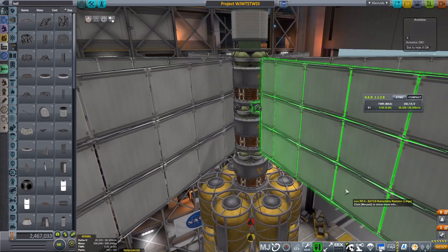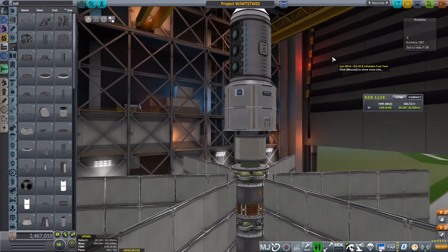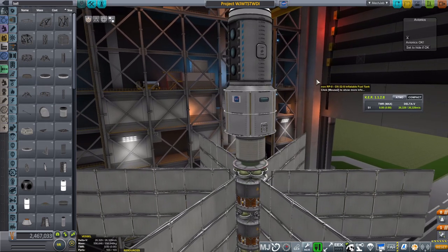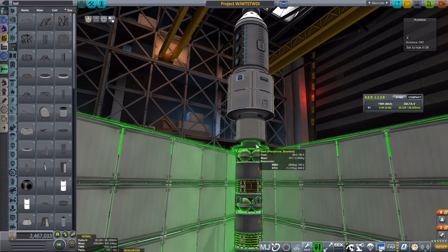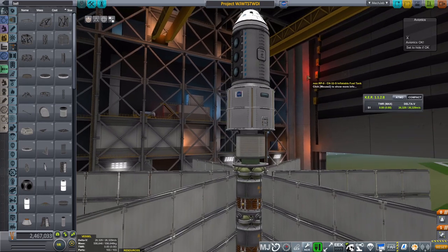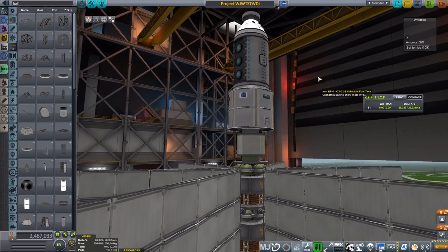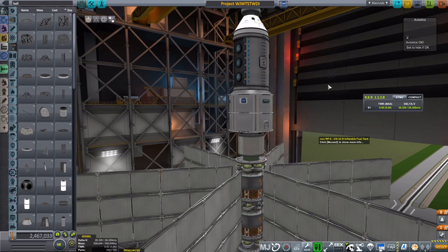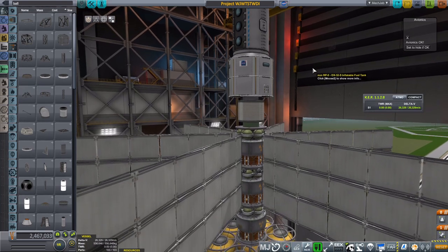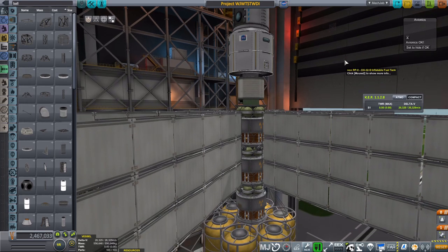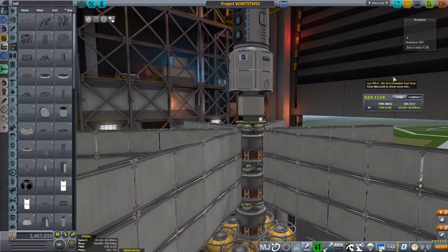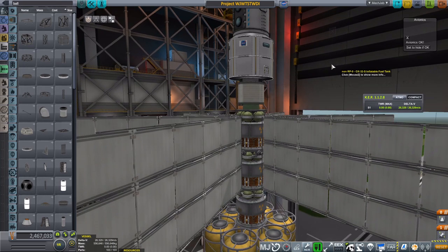It's a little complicated, but in order to undo it, you can have little thrusters oriented radially around the craft. You burn a little bit of fuel, and then you spin down the wheels so they can get back to working again. So that was mass meant to compensate for that. The engines themselves, I didn't have time to throw in the positions and such. But you can imagine like the Apollo Command and Service Module, those RCS block engines, it'd be something similar to that, oriented and placed in good places around the spacecraft.